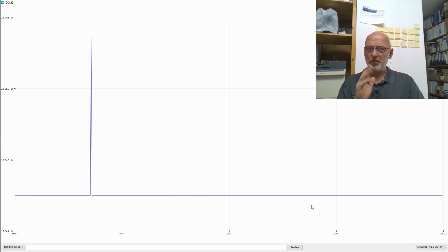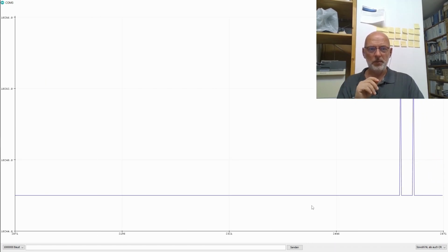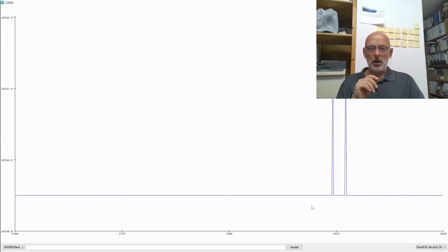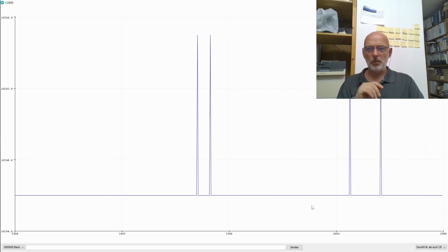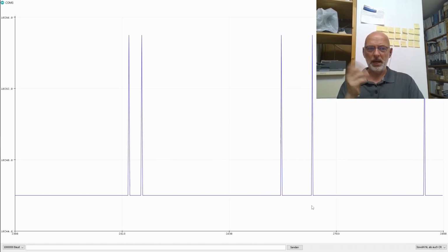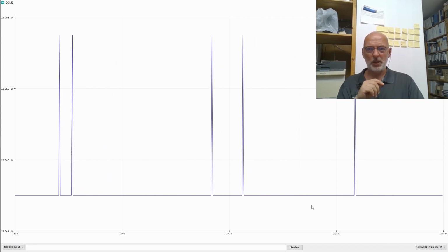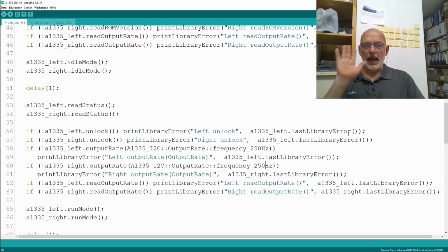It was there, believe me, just before I started recording. Now we're back at 0. Or let's just call that 1 LSB. I mean, maybe I was hallucinating. I don't know. And finally, the maximum averaging over 128 samples that we can do here. Output rate is now down to 250 Hertz.